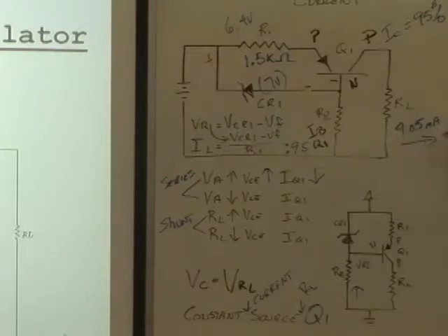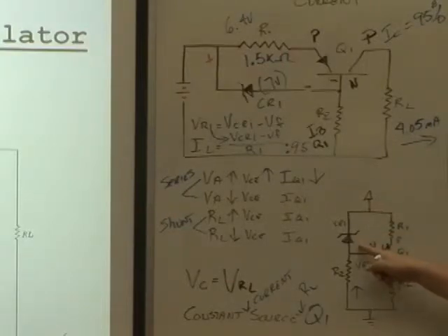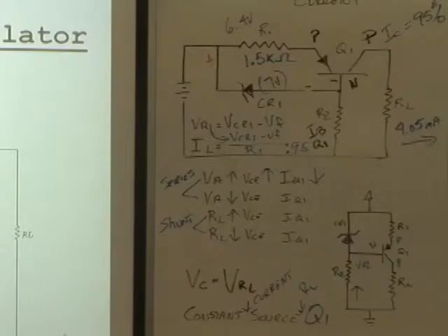Because I don't want this current to do this, do I? No, sir. I want it to stay relatively constant, but if I increase the line, total current goes up, doesn't it? Yes, sir. So the circuit automatically senses that, and based on how it's configured with this Zener diode here, because it's keeping this top half of the circuit relatively constant, R2 is the one in this circuit that, for the line side at least, increases or decreases the potential on the base. It's going to control what Q1 does. You make it conduct more or less. I like that. Good. That's how this one works.